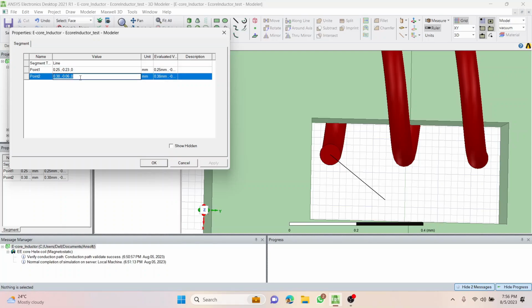What we would want is to copy and paste in the second point, and do a few changes. Now if you see the scale right over here, this extension should be in the Z direction, and in the positive Z direction as this coordinate suggests, right? So I would like to add Z direction, and that would be positive Z direction, maybe 2 mm, right?